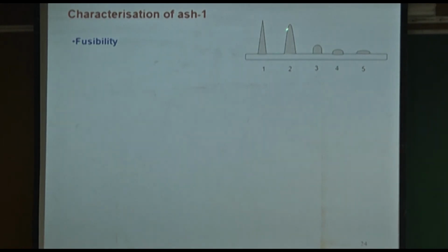So initial deformation temperature is this, sintering temperature is this, and this is the melting temperature. Based on this, the boiler manufacturer, and this is very simple, relatively cheap to do these days compared to the early 90s, I would say. You can actually literally see what's happening. You can record it, and you can pinpoint within plus or minus 5 degrees what the temperatures are.